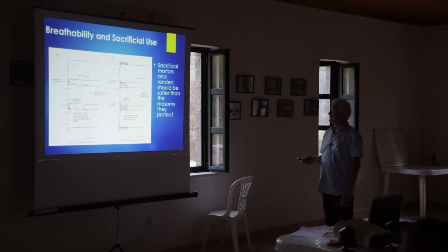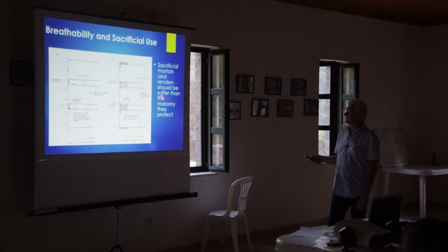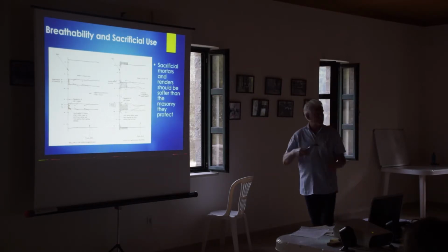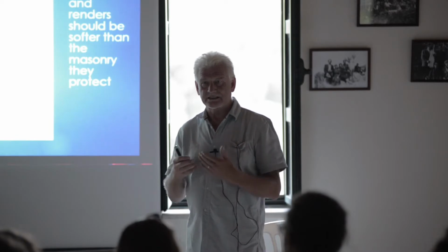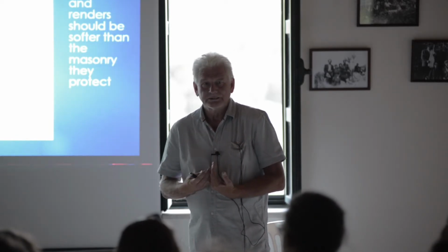Breathability and sacrificial use. Sacrificial mortars and renders should be softer than the masonry which they protect. That's a rule.